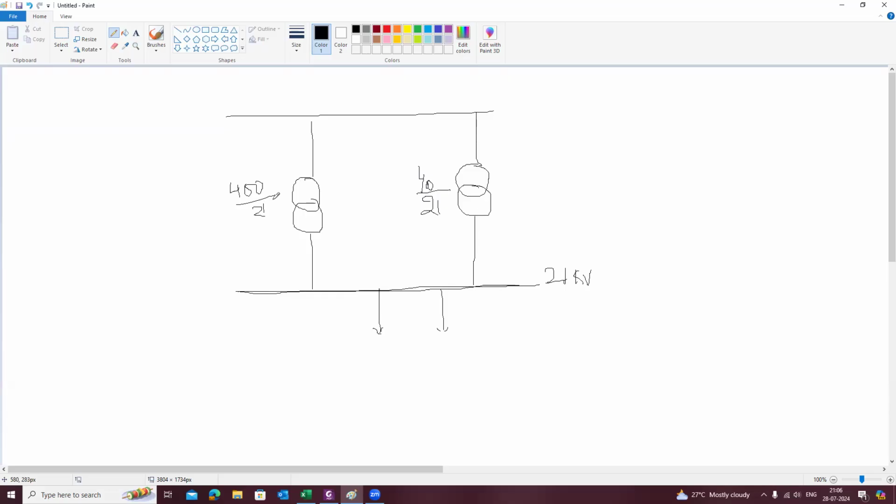The purpose of the automatic voltage regulator is to maintain the generator terminal voltage within the predefined limits. How will the AVR maintain the terminal voltage at the generator? In the AVR, you have two functions. One is, it works just like a comparator. In simple terms, it is like a comparator. So two inputs will go to the comparator first.